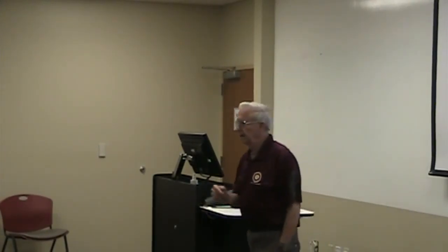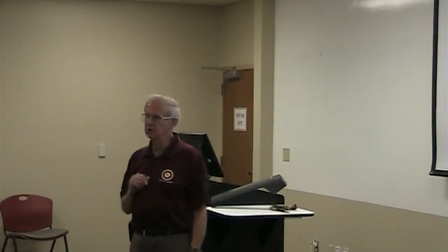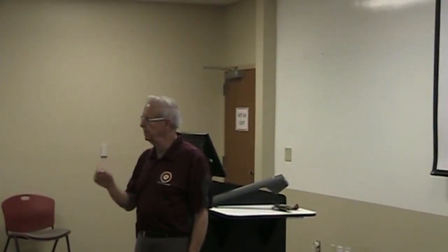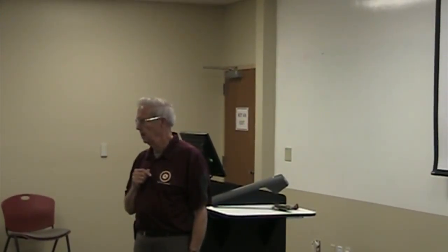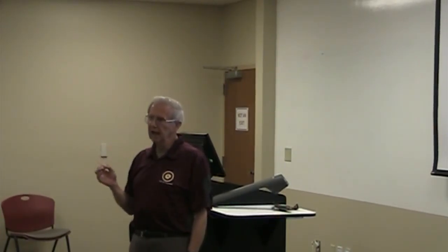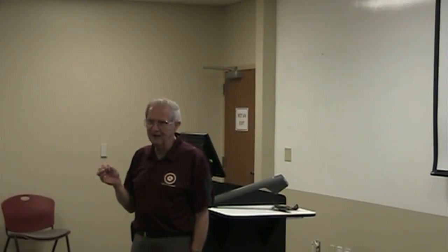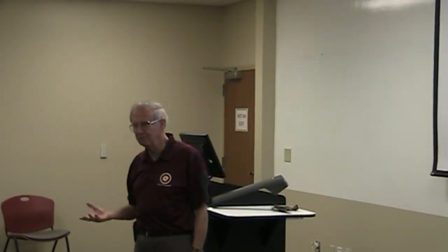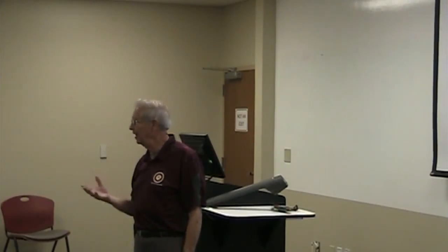Anyway, he came up with a plot for the twin Comanche of VMC versus weight. And what he showed was that the VMC at a light weight, where most everybody was flying to do this test and the demonstration for multi-engine pilots, was actually above the published minimum control speed.